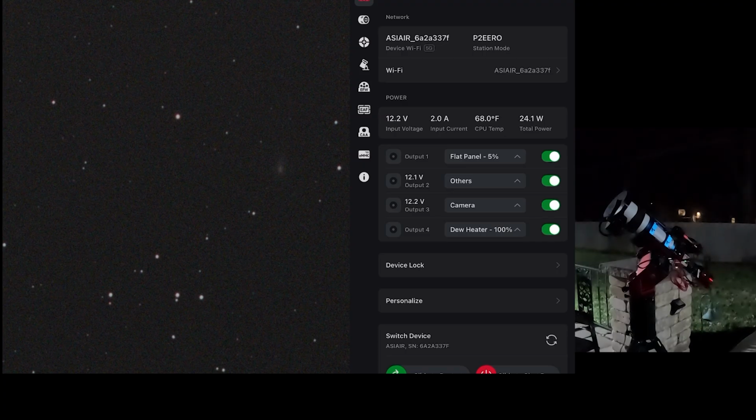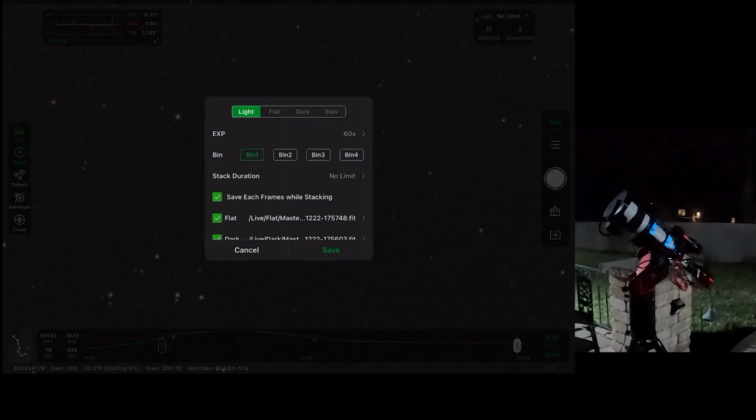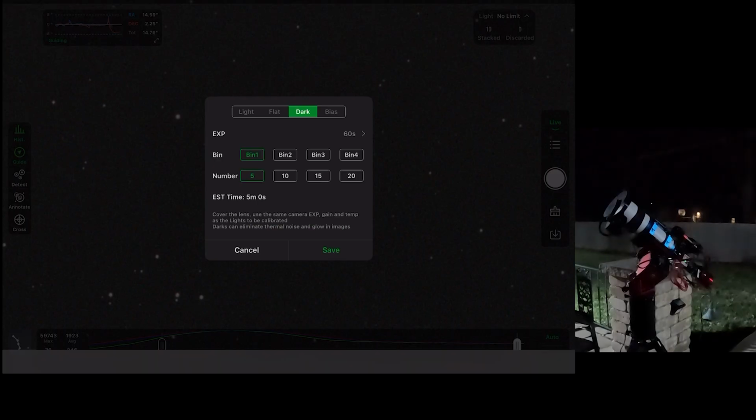Dark frames are used to remove thermal noise and hot pixels. At any given temperature, there will be an energy distribution in a semiconductor. The fraction of electrons with energies greater than the 1.1 eV bandgap of silicon will contribute to the thermal noise.